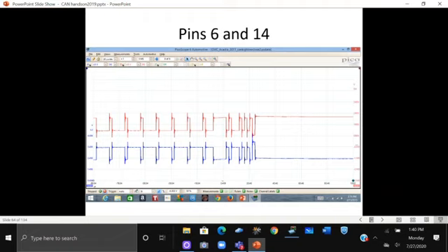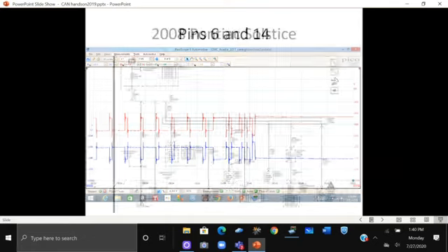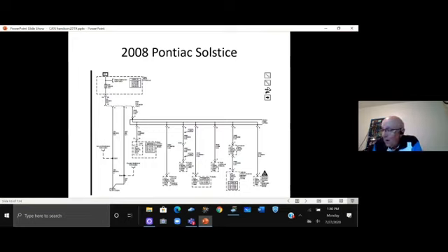Okay, so now back up. What did we do first? We ohmed it out. Then we look for the wake-up signal. Then we look for the mirror image. Important, teach the student to stop if something is not right. You don't go and look for a wake-up signal if you don't have 60 ohms. You don't go and look for a mirror image if the system doesn't have a wake-up signal because it's not on. Okay? The last piece of this involves using a scanner.